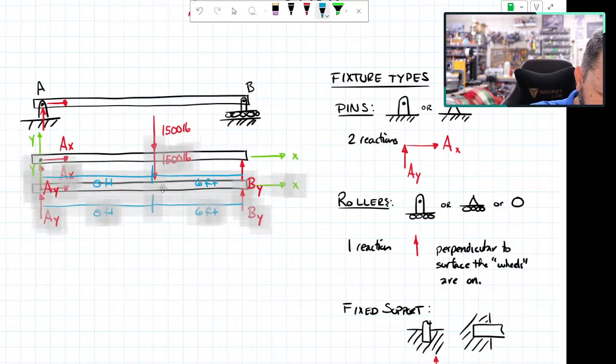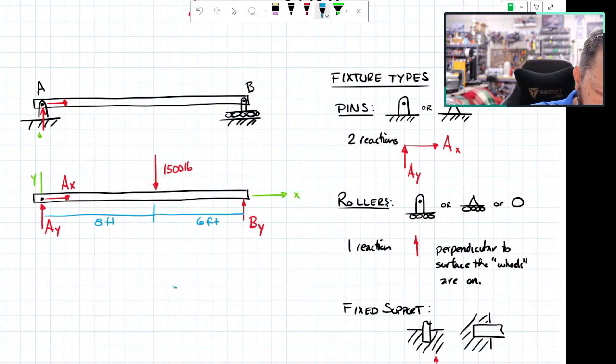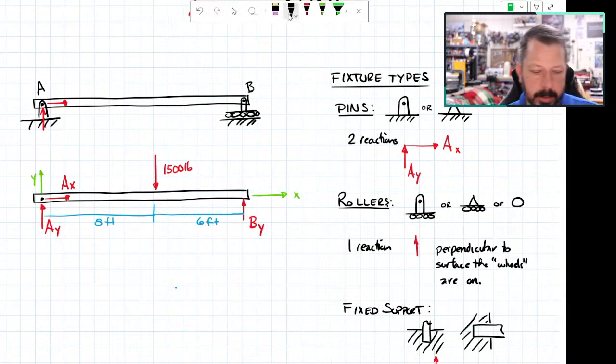So move it down there so it's not as close to the other one. Didn't get the little arrow there. Okay. So I've got a free body diagram. It has the body, which is just the beam. It has all the connections where it was connected to the world replaced with just forces. It's got a coordinate system. It has dimensions. It has variables for the unknowns and values for the knowns. It has units. So it's a good free body diagram.